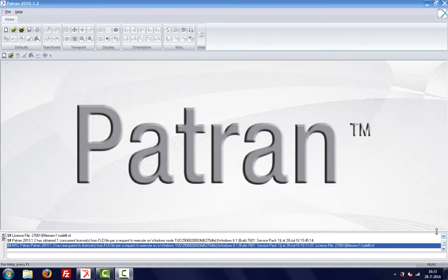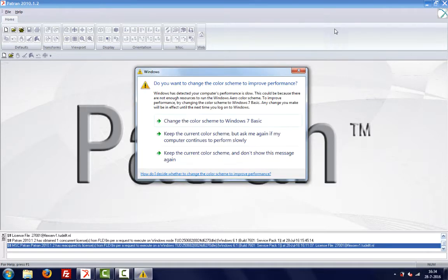There are other solvers also that are available for use with PATRAN. So, for example, you can also use the Abaqus solver after making a model in PATRAN. That's easily possible. But the combination we are going to work with mostly is PATRAN Nastran. Nastran is good enough for linear analysis, so we don't need to look further. Nastran is good enough for all kinds of other analysis as well. But you will see that there are some other options like Marc that are suitable for specific problems, as you would continue working on this in the future.